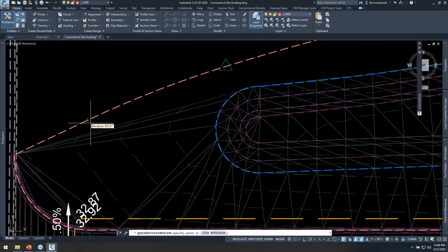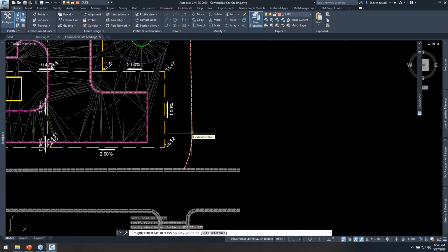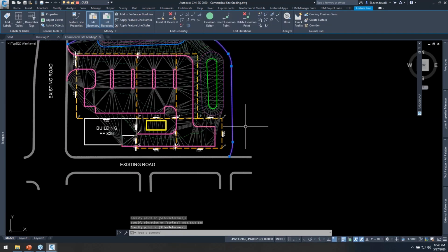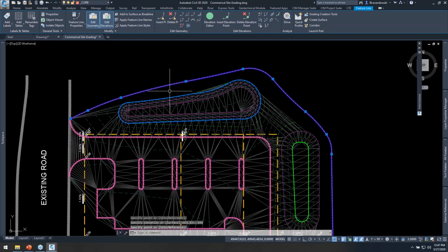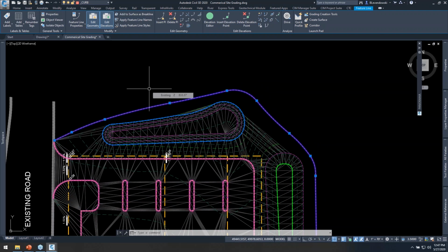I can make a couple edits here as we see fit. Maybe that feature line here, right? So you're defining some general grading limits. Even without Autograder, this is an approach I've used where you have not just your daylight line off your main components, but some kind of middle line there where you then daylight from that.